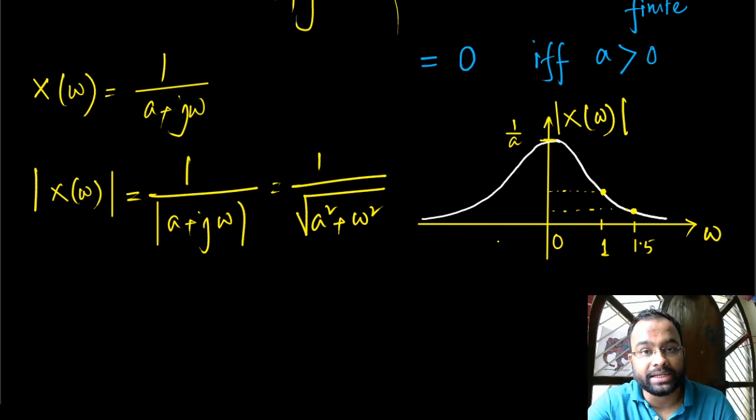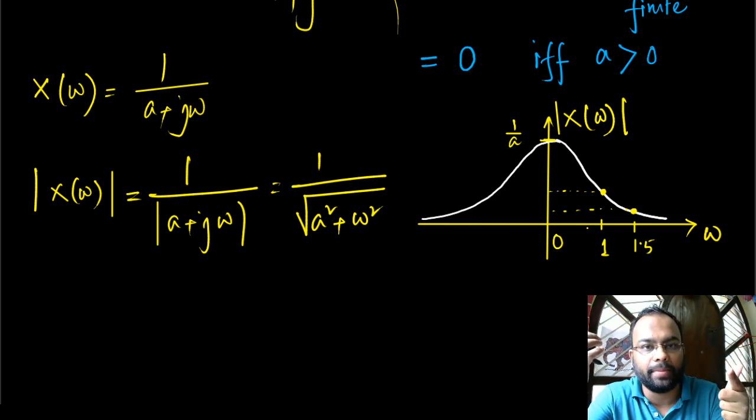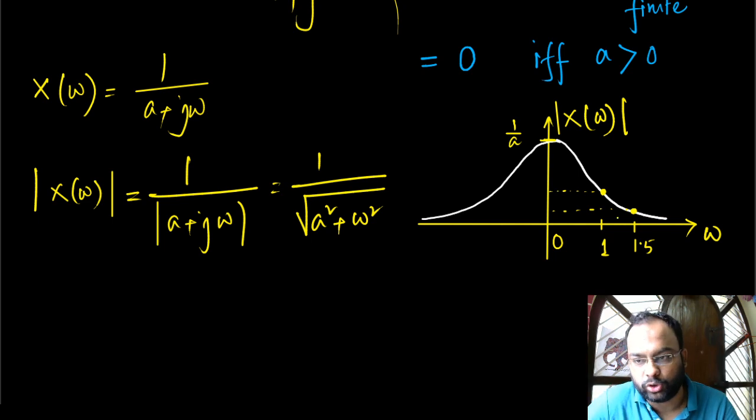But unlike periodic signals, all the intermediate frequencies are also available. Now if I ask you what is the next frequency after 1 radian per second present in the signal, it is not like the concept of harmonics. In our earlier Fourier series examples, we had a fundamental frequency, and every other frequency was just a multiple of the fundamental frequency, namely a harmonic. But here all intermediate frequencies are available because frequency is a continuous variable here. So there are infinitely many sinusoidal components between any interval you might want to choose.